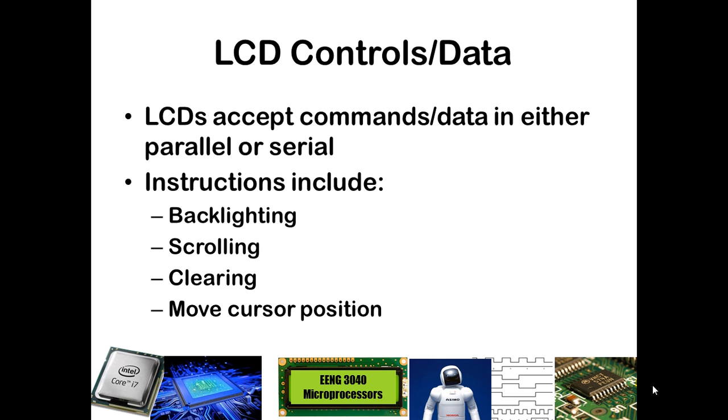And the interesting thing, LCDs in general accept either serial commands or parallel commands. So it really just depends upon what type of LCD panel you're using. In this case, we have one that accepts information in parallel.